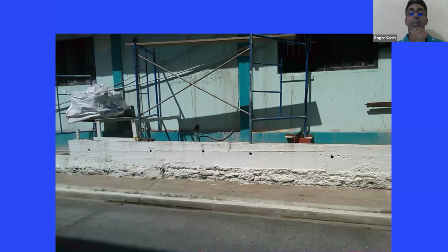And this one is a scaffolding. As you can see, the bottom of the scaffolding is an H-frame scaffolding. It's not properly secured. They have made it up with brick, and in this one, they have placed it on a ledge. So it's a lot of non-conformances, non-compliance that was immediately flagged. There's only one working plank at the top. With scaffolding, the working surface must be fully planked.